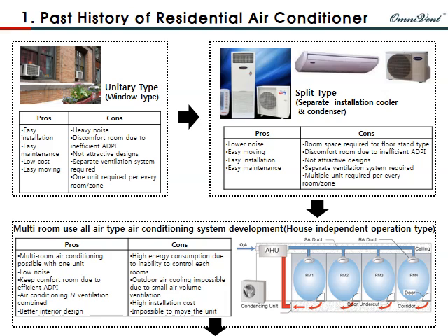However, it is impossible to operate individually as a room-independent air conditioning system, as while operating all zones are air-conditioned at the same time, therefore causing high electric consumption. Furthermore, outdoor air cooling is impossible due to its insufficient air change rate ventilation. It also causes higher installation costs due to additional ductwork.